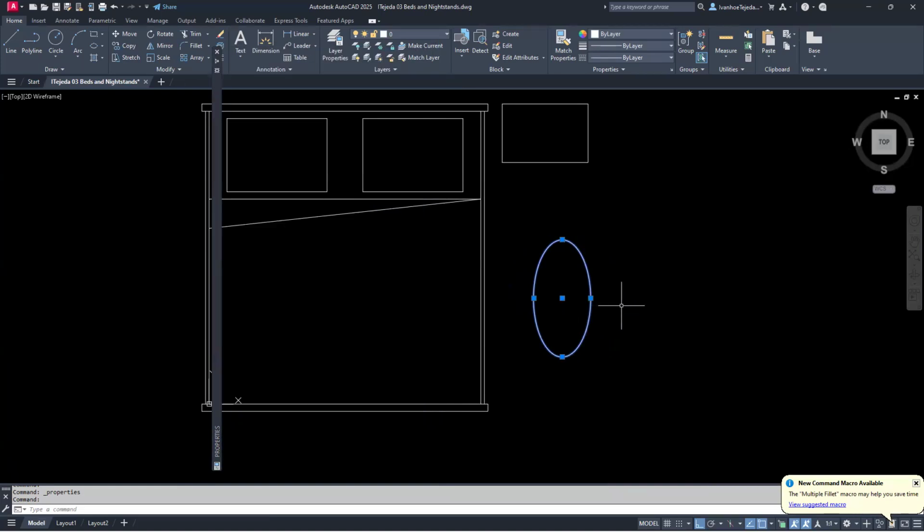or you can do it the way I did it. Or perhaps, now that you know how this works, when you go to draw it based on an axis and endpoint, you now know, like I do, that I can pick the first point and I can make this 2 foot 8. And then for the other axis, I thought it was the overall length, but it's not. I need to give it half the distance. I type 8 and enter, and that would have done it. So I'll go ahead and take this one, delete it, and then my properties window.